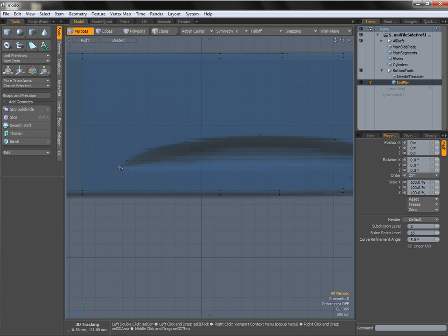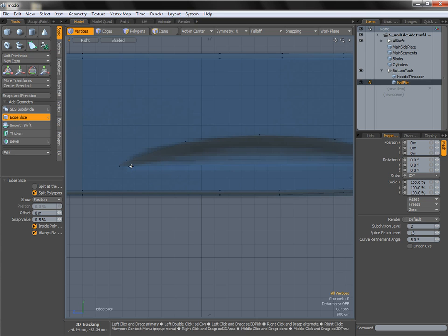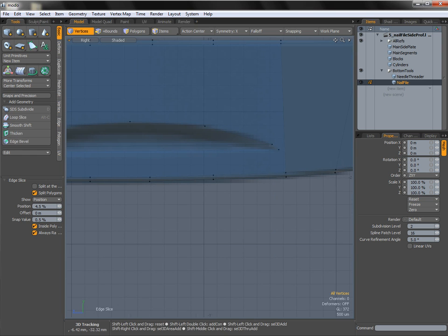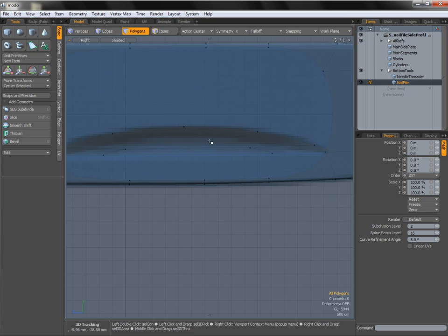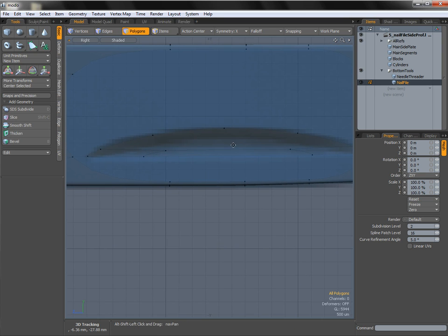However, as you can see, we have no support edges going this way at present, so these verts, if I go to tab mode, get pulled in towards the middle. So we want to stop that from happening as well. So what I'm going to do is come in and add an extra edge like that, and do the same on the other side. So we have this square and this square here. And if I go to tab now, you'll see that we've got these points exactly where we want them. It's just the rest of this object that we now have to figure out.